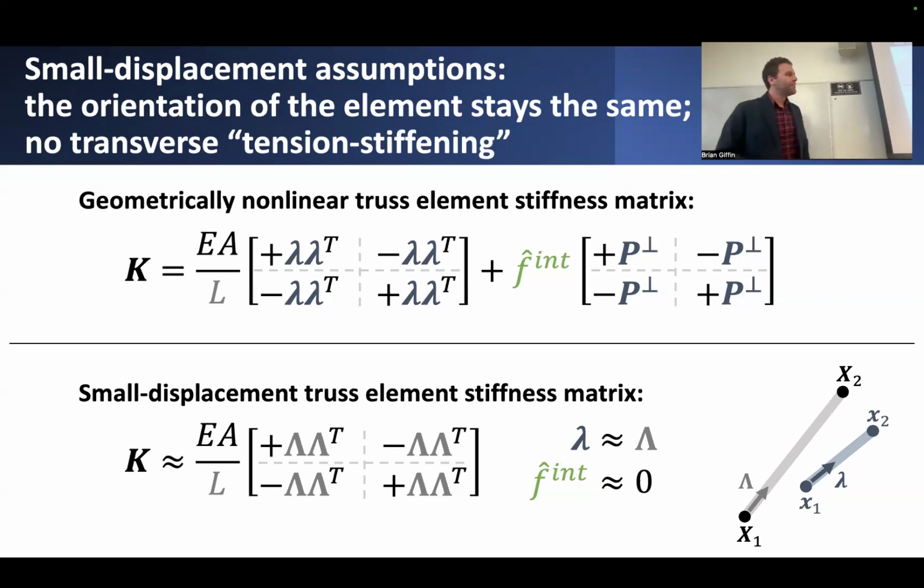And also, let's assume that we can get rid of that extra term that involves something with respect to f hat. Let's just assume then that f hat, the internal force in this member, is close to 0. If we do that, we recover this expression. And it may not look familiar to you, but if we were to manipulate things around, we could actually show that this is equivalent to that typical expression we had that involved the geometric transformation matrices from global to local coordinate frames in this element.